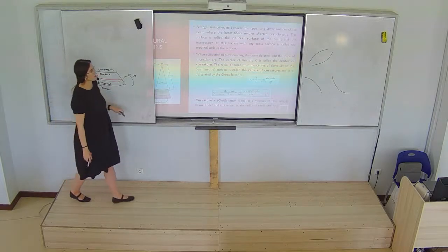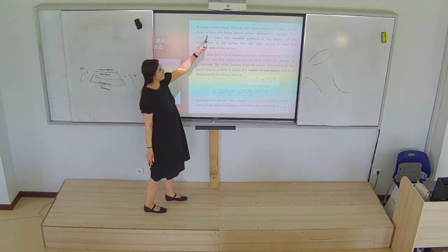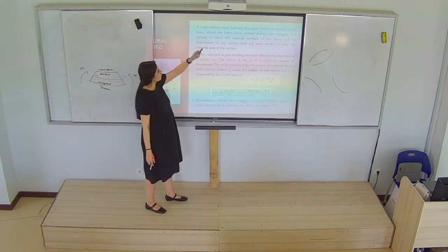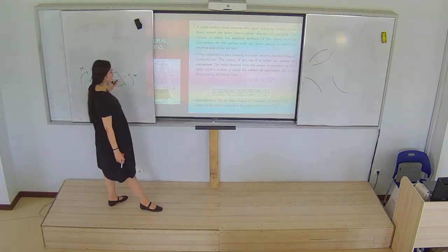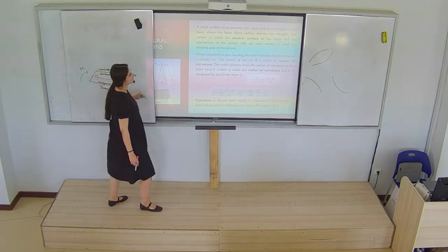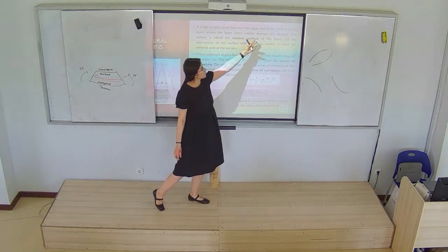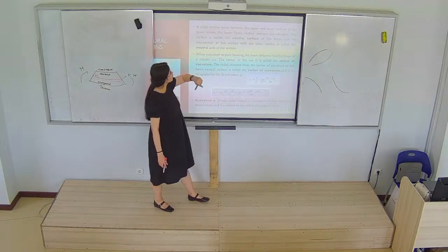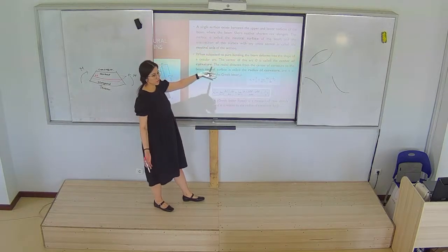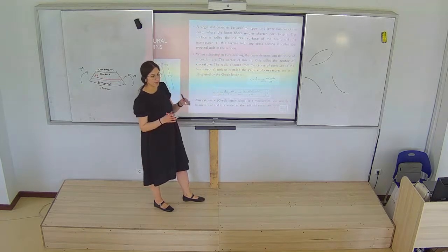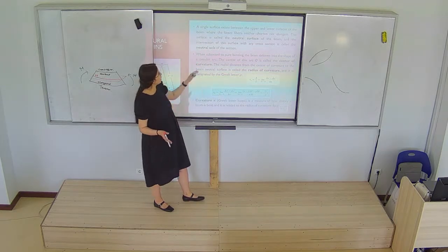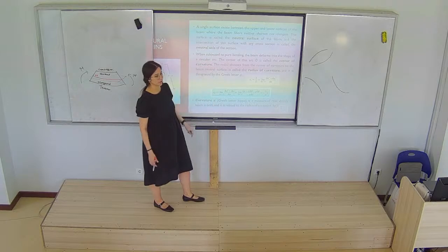So, in this case, this definition is the same. The neutral surface exists between the upper and lower surfaces, always. And it doesn't have any shortened or elongated conditions. So, this surface is called the neutral surface. And the intersection of this surface with any cross section will be the neutral axis of the section.